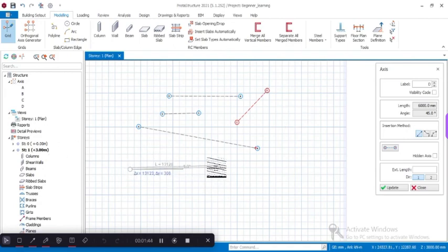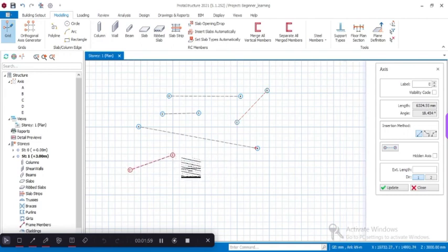Then if I'm using delta x and delta y, let me go back here. I'm drawing another line with Shift F2. That's 6,000, comma 2,000. So the comma is the notation for delta x and delta y, 6,000 being delta x and 2,000 being delta y. So the point will automatically be picked for me. So this is based on axis, and this is based on the length and angle. Then after specifying the length and stroke angle, pressing Enter or left click will accept the end points.